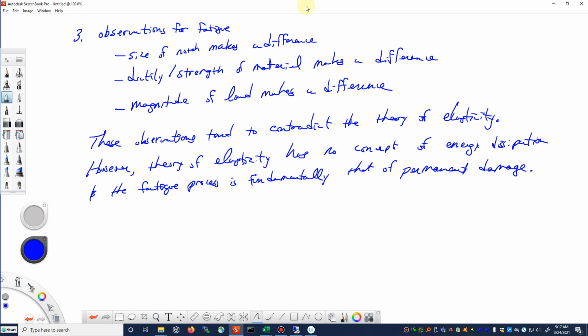Strength and ductility are kind of trade-offs. It's a classical trade-off in materials. You can usually have something that's ductile. When you increase its strength, you make it less ductile. Ductile materials tend to be able to sustain high levels of plastic strain easily. Strong materials usually are able to sustain high levels of elastic stress and strain very easily. So you have a trade-off on both edges of your SN curve, if you will.